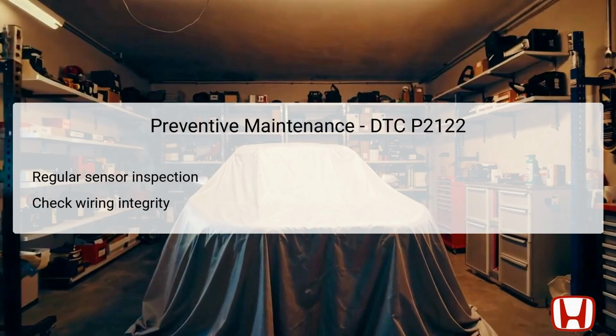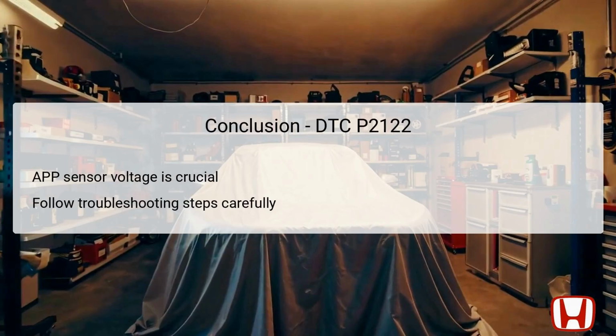By implementing these preventive measures, vehicle owners can minimize fault occurrences, ensuring that the APP sensor operates smoothly and efficiently without triggering diagnostic issues in the future. In summary, the DTC P2122 highlights a critical fault condition associated with the Accelerator Pedal Position Sensor A circuit, indicating low voltage that impacts engine performance.